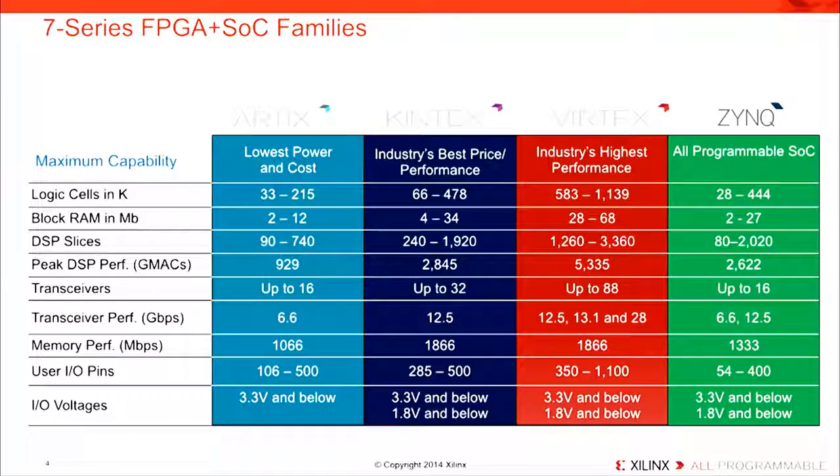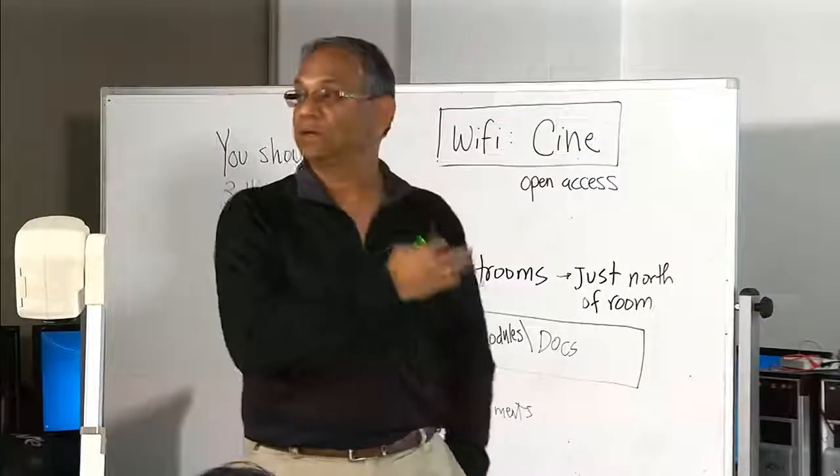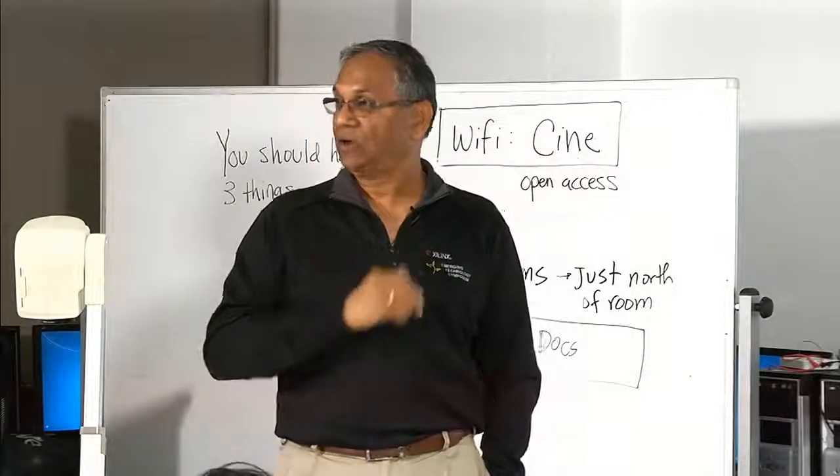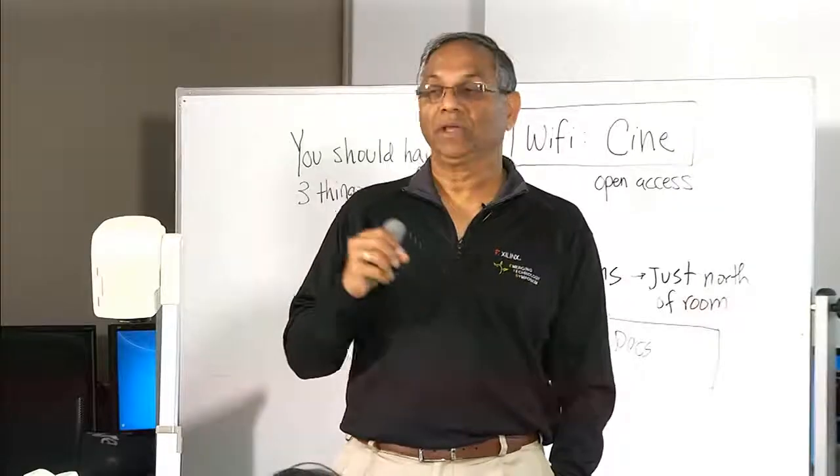If they are 2.5 volt compliant, you can configure them as 2.5. So all IOs are 3.3 volt compatible. In the FPGA, do we have any tri-state buffers within the chip? And the answer is no. It gets translated as a multiplexer.